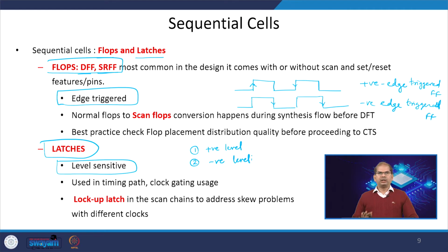Now that we have talked about flip flops and latches, we can talk about scan flops. Whenever you are designing any kind of digital system, we have very few pins, but we are interested to know what is happening at each and every point of the chip. The reason is that if the chip is not working, how can I debug any part of the chip? What is the value of the nets inside the chip?